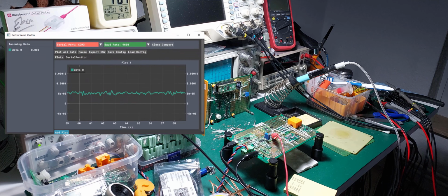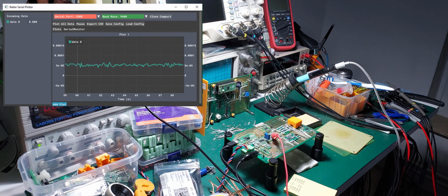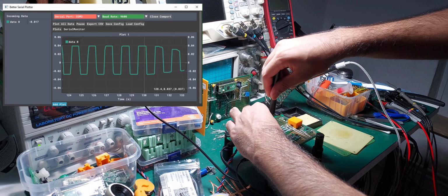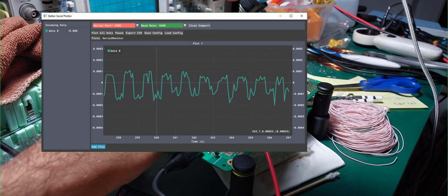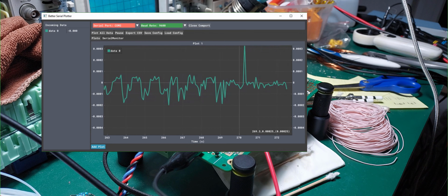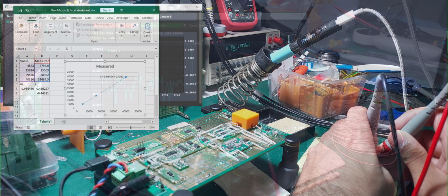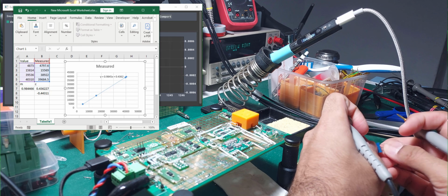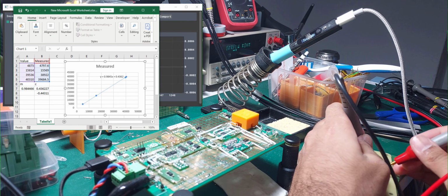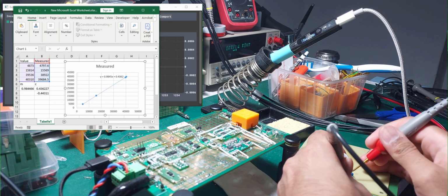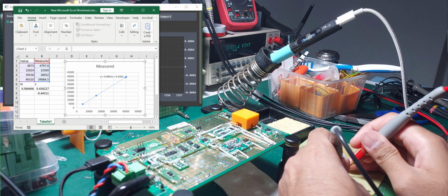The easiest way to measure CMRR is to short the FDA inputs and feed the biggest square wave my function generator can output, 20 microvolts peak to peak, and continuously plot the ADC readings while carefully trimming a potentiometer. Once the square wave has disappeared into the noise floor, the CMRR is almost fully gone, down below minus 120 decibels. Now, the potentiometer's exact value can be read to the highest resolution possible with my Keithley 2000, whose resistance ranges are unfortunately out of whack, so a simple calibration using some hand-me-down resistors is necessary, with the linear transfer function determined and back-calculated using Excel.